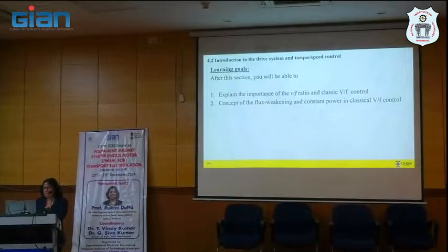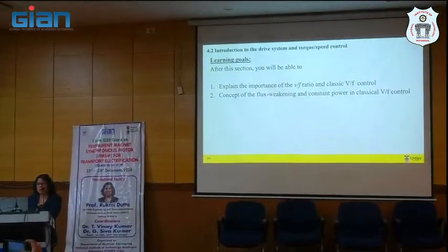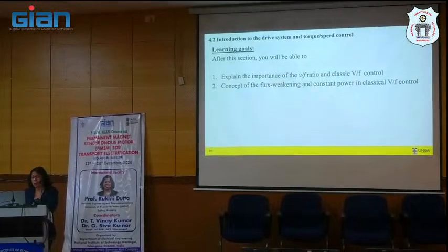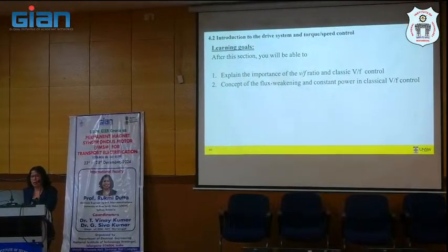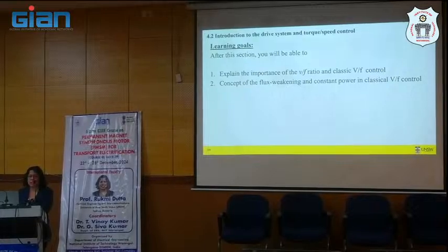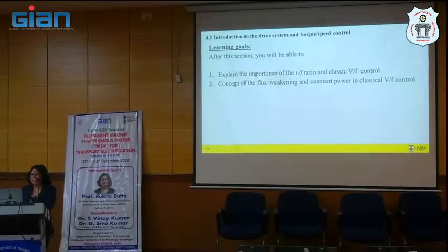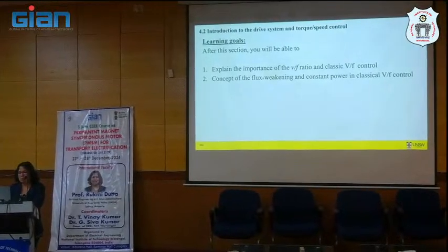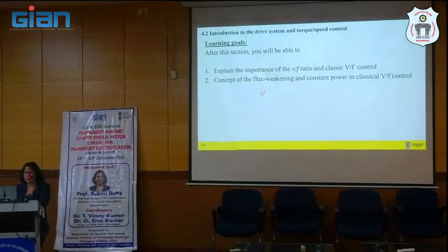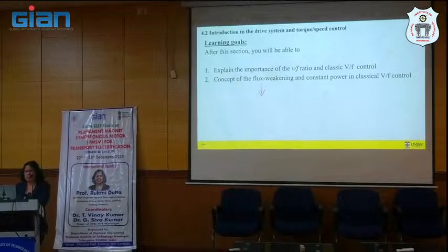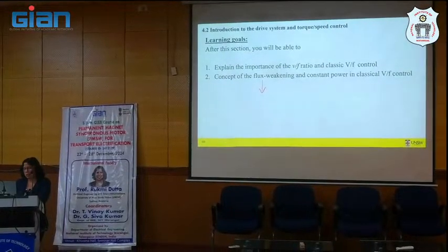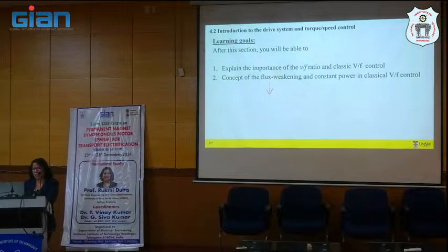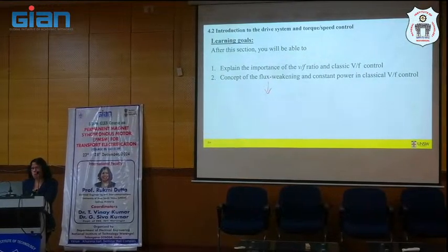So that's why first we will be looking at the control. We will start with classic V/F control, and then we move to how the concept of flux weakening and constant power is in classic V/F control, and then we will probably move to some more advanced ones, okay? FOC, field-oriented control, or DTC or MPC, etc. So today's talk actually would continue to tomorrow.